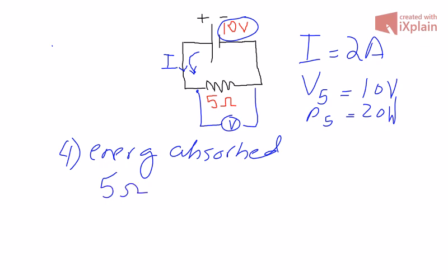Now remember, the 5 ohm resistor, when you touch it, it's going to be a little warm, okay, because it has current that's flowing through it. Now remember, the formula for energy is simply equal to the power that is being used by the 5 ohm resistor times time. Now in this one particular example, let's assume we run the circuit for 60 seconds.